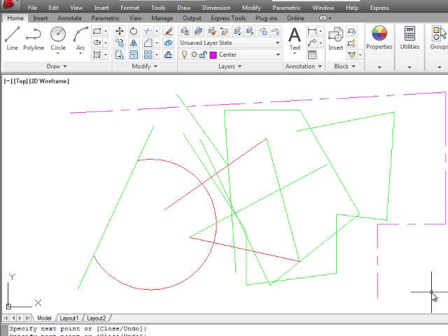We'll talk about layer scale a little bit later as far as scaling the line types, but this is a good start for our layers. You can create brand new layers. You can have as many layers in a drawing as you need to have to keep your drawing organized the way you want it to. And you can, again, turn them on, off, freeze, thaw, lock, unlock, make one current, change the color, and change the line type.